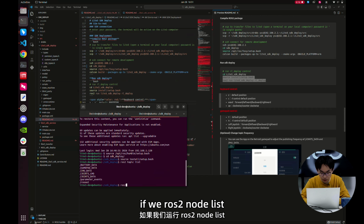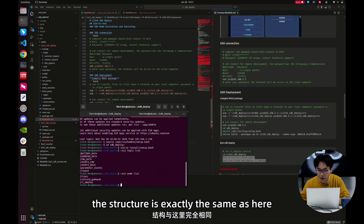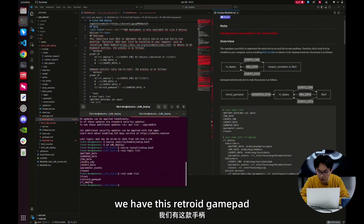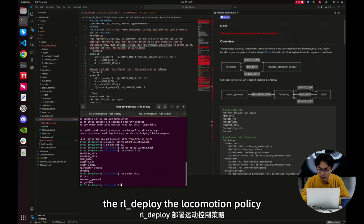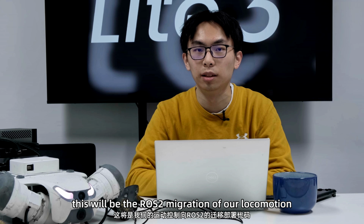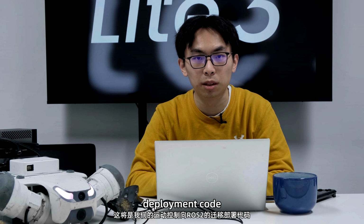So if we ROS2 node list, we can see that there's 3 nodes. The structure is exactly the same as here. We have this retrain gamepad that's getting the data from the gamepad, the RL deploy, the locomotion policy, and the Lite3. Lite3 is the transfer node, it's getting data from the low level. So this will be the ROS2 migration of our locomotion deployment node code.